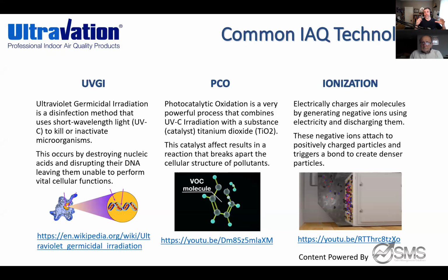In this example, though, that's how you can create an even stronger effect inside of an air supply. Besides just having UV lamps, per that video, if you have products with the PCO photocatalytic oxidation upgrade, you're actually creating an invisible field around the device. As the air is passing by, it's also helping break down odors and other components like car exhaust and even cooking odors. It's just an added benefit, especially in a residential application. Later I'll show you a couple of products that use that level of technology. Besides that, the other thing we wanted to define here was ionization.